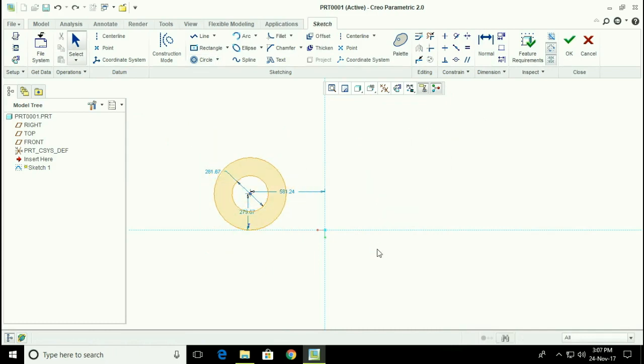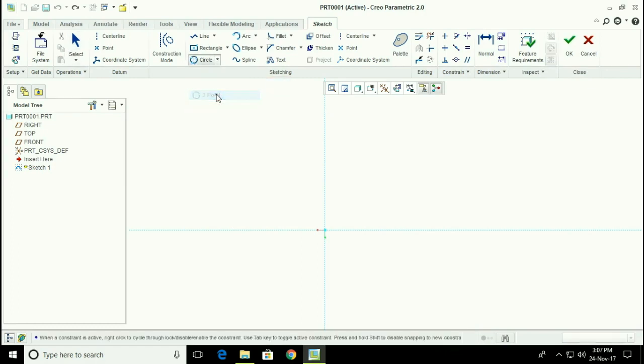With the 3-point circle tool, you can draw a circle with 3 points or 2 points. On a freehand sketch, 2 points may be used. For a circle inside an object, the 3 point circle is used. So now we are going to be drawing a diagram in free sketch. First point, second point, I will draw a circle. 1, 2, and we have a circle.